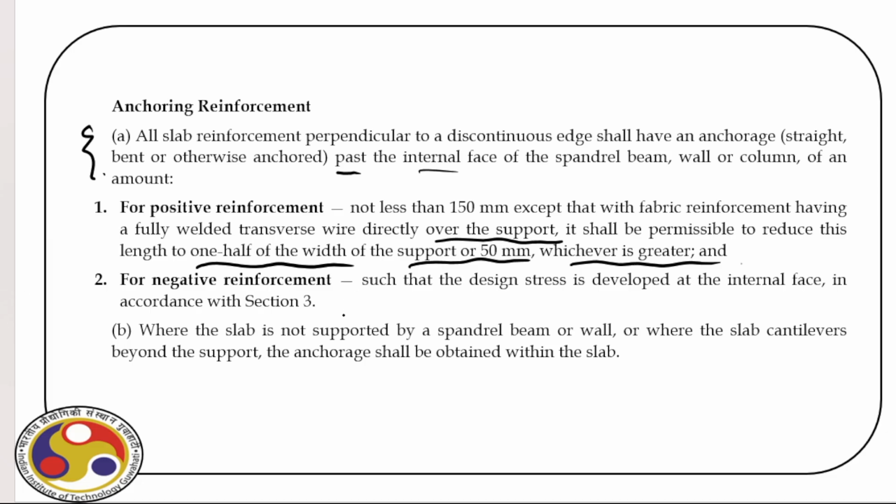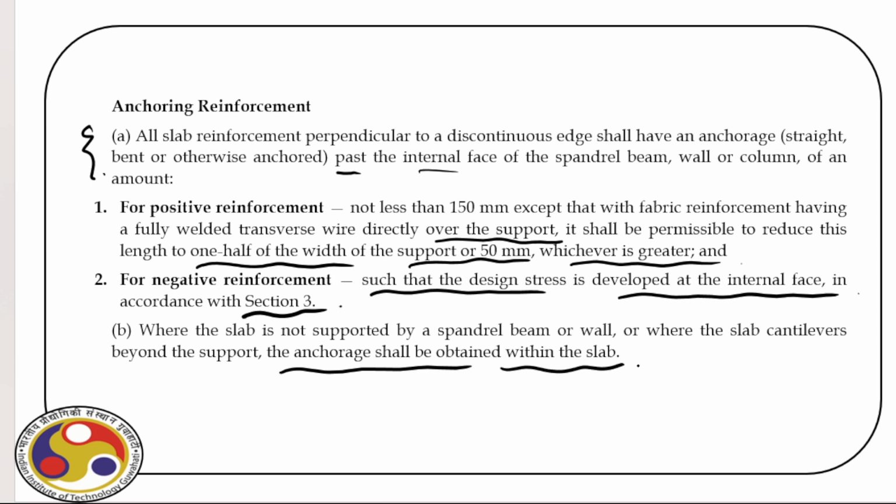Then for negative reinforcement, such that the design stress is developed at the internal face in accordance with, we have already discussed that earlier in section 3. Where the slab is not supported by a spandrel beam or wall, or where the slab cantilevers beyond the support, the anchorage shall be obtained within the slab. Right.